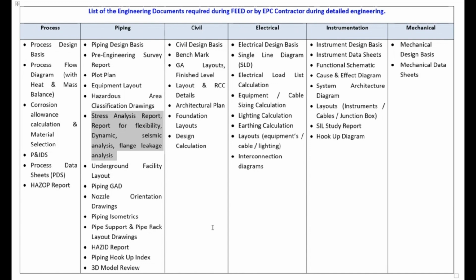See, you cannot stop the compressor vibration from transmitting to the piping. That is next to impossible. So the vibration will be there. But your piping system should be able to address the vibrations which are coming. Of course, the compressor vibration should not go beyond a certain limit. That condition monitoring system will be handled separately. The compressor should not vibrate unnecessarily beyond the designed limit of vibrations, okay?